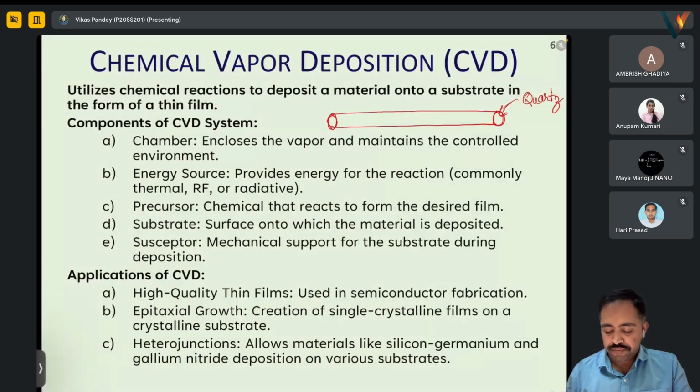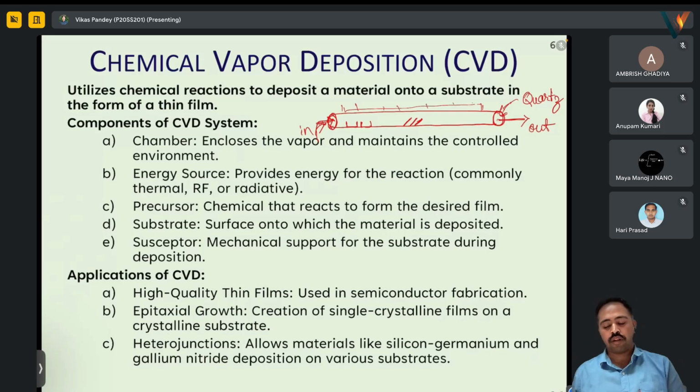And in this, there will be an inlet, an outlet, and then here we will keep our wafer on which we want to deposit. And there are two ways that you can insert the reactants or precursor, as it is said, either mixing with the gas or you keep them here. And this whole thing is getting heated. This is a very simple CVD I am talking about.